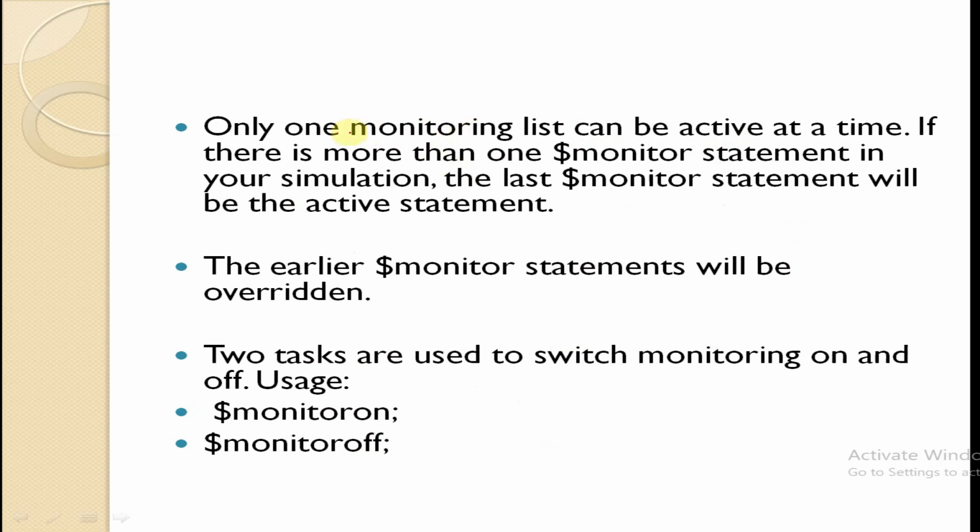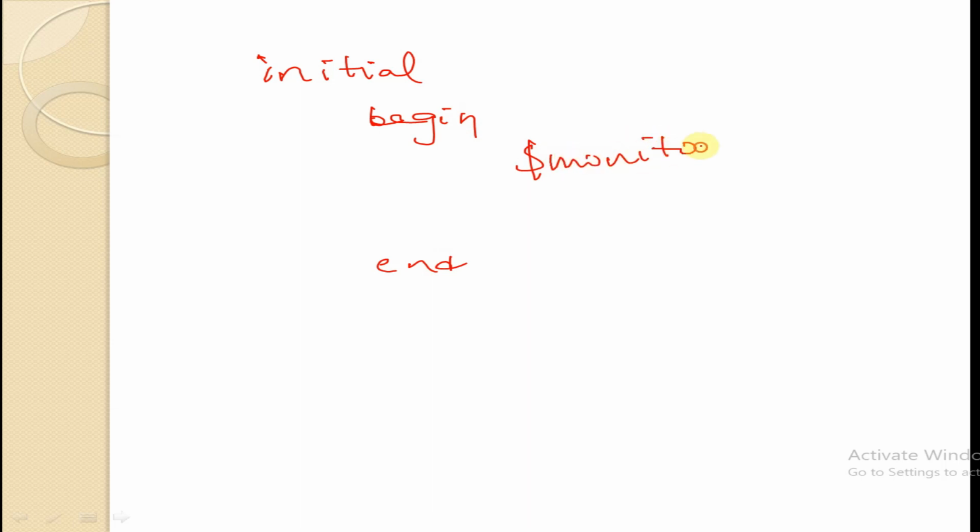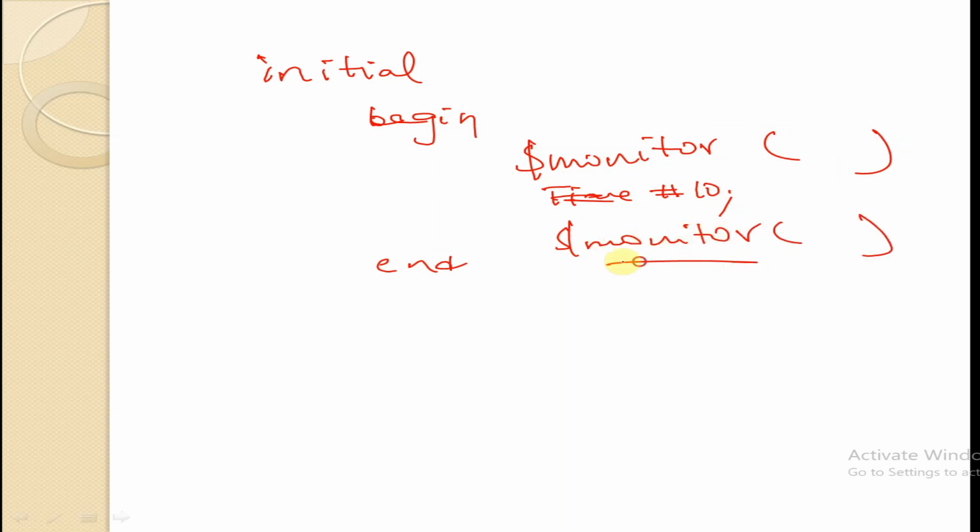And if we have two $monitors in our module, for example in an initial block, two monitor tasks with some time delay, say 10 time units, then the last monitor will be the one updated.